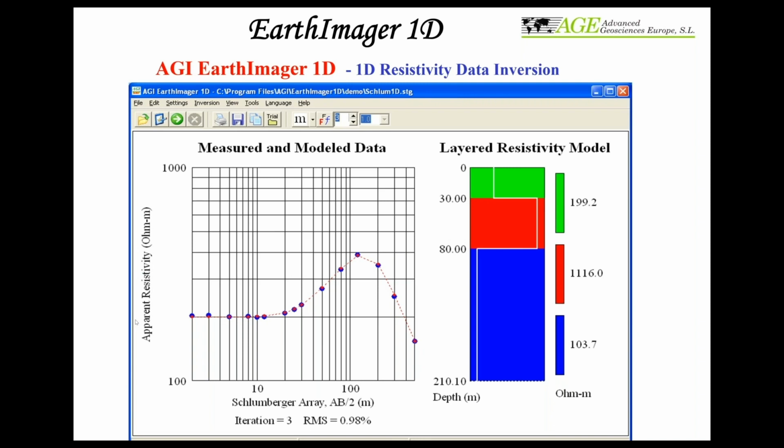But don't do it exactly at the borehole, because sometimes the borehole has a metallic casing, and that will give you some noise on your measurement. Try to stay a little bit apart from the borehole to get your data there. The borehole information will be good information for the starting model of your inversion. Try to obtain a good result and compare it with the borehole outcomes.